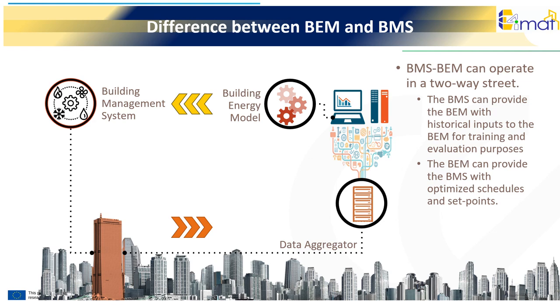First, providing historical inputs to the BEM for training and evaluation purposes, and second, receiving and applying optimized solutions obtained from the BEM. However, many BMS systems have limited capabilities in this regard, i.e., do not have large data storage capacity, or have limited communication protocols. As their primary focus is real-time operation of the building, they require some level of intervention to update their capabilities and work with BEMs.